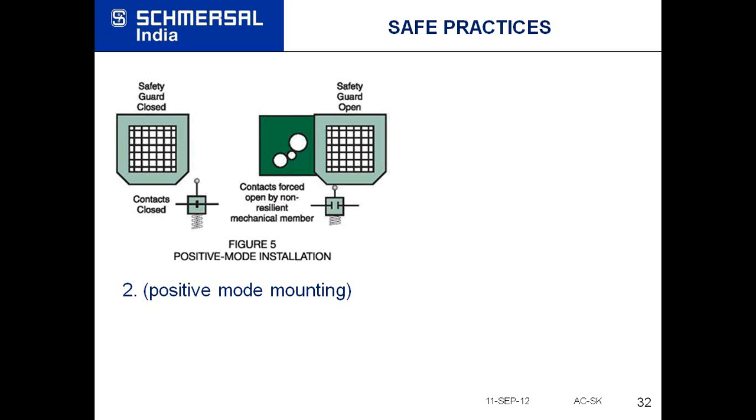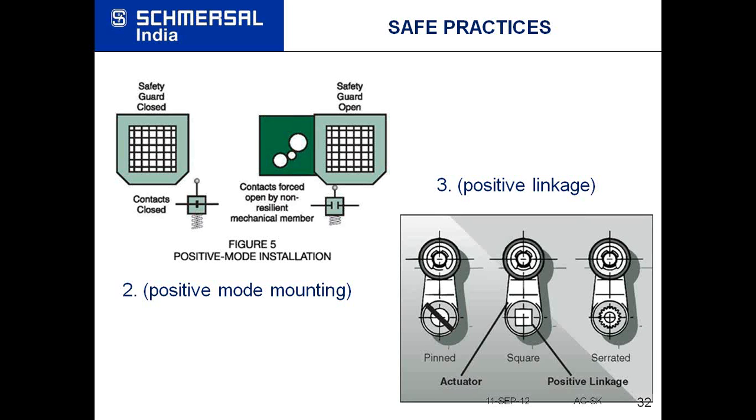Okay. Similarly, we should have a positive linkage when we have a limit switch for safety application. And for this positive linkage, you can see in the diagram, there should be a pin, or the shaft where the lever is mounted should be square, or it should be serrated. Otherwise, the lever may slip and the contacts may not break. So any limit switch which doesn't have any of these three requirements is not suitable for safety applications.